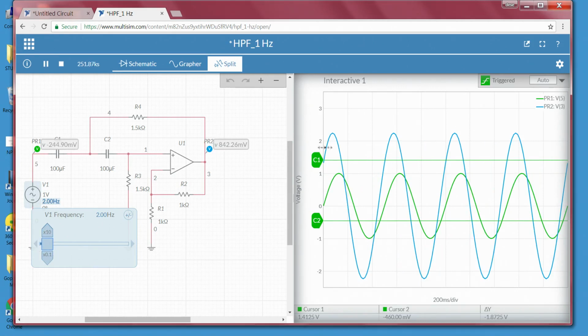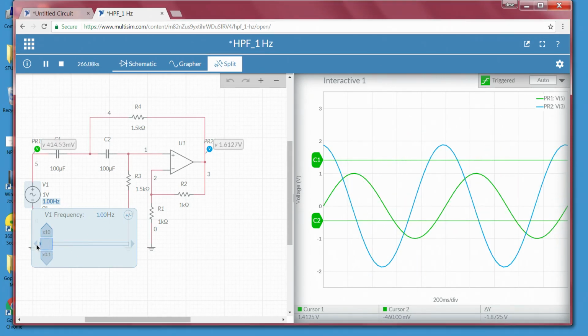Now, if you carefully observe our characteristics, whenever it comes close to the cutoff frequency, the amplitude is a little higher, even here we can observe at this point. The gain should be 2, but there is slightly higher gain at frequencies close to the cutoff frequency. This is because it is a second order high pass Butterworth filter. When we recall our Butterworth filter characteristics, the gain is slightly increased near the cutoff frequency. The same thing we can observe here too. Slowly decrease again.